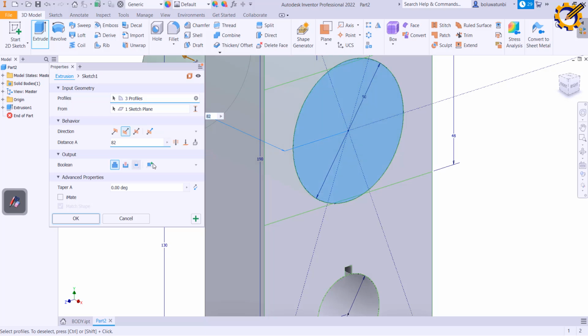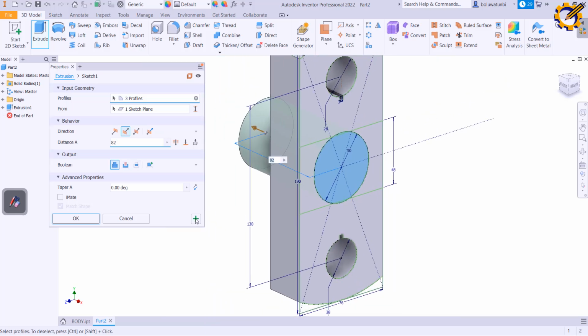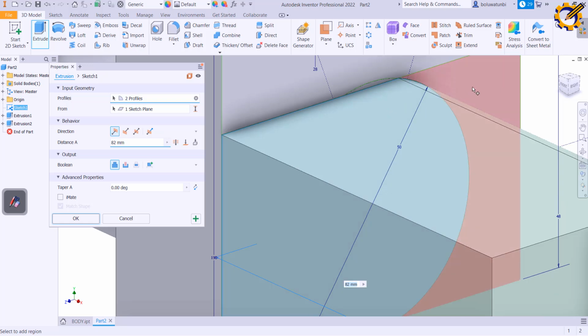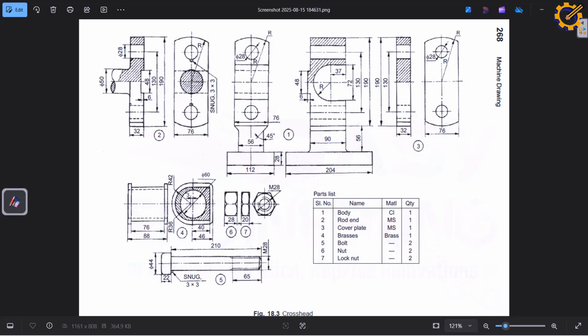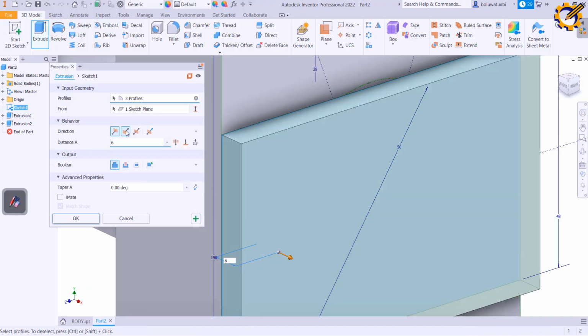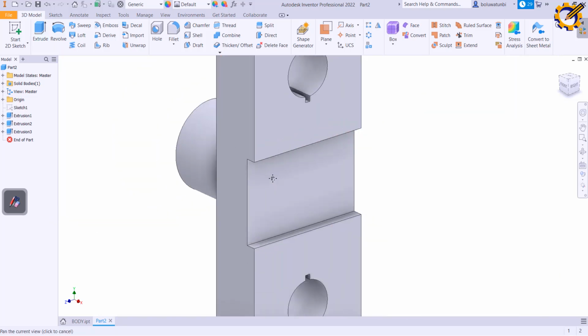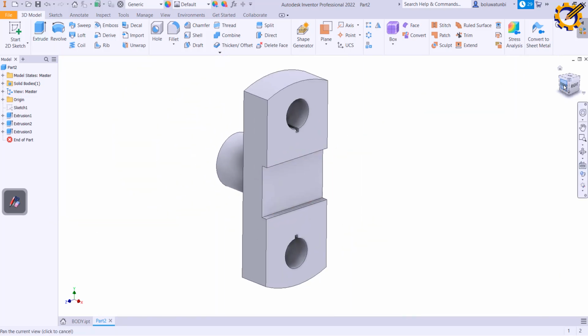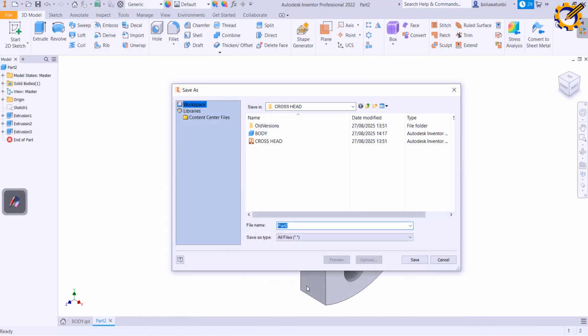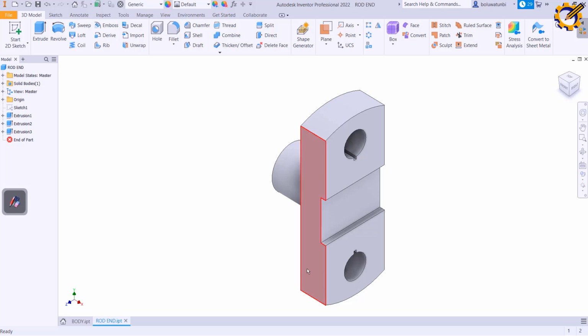I'm actually going to make it solid. Towards the back here, I'm going to press my continue. And now I'm going to pick this aspect, and this aspect at a distance of 6, but now on the inside here. So I have this object right here, clean and fresh. I'm going to save this as, what's the name? Rod, and enter. So that's settled.